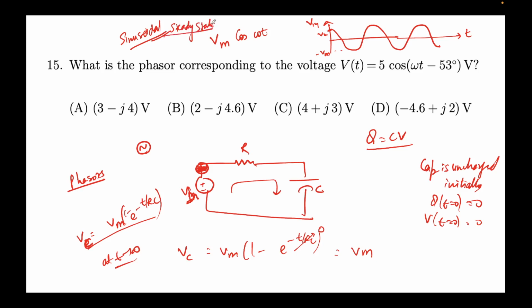This means that it's oscillating nicely over some reference like this. The output would, just like the input voltage, be sinusoidal, yes. It's not constant. It's varying with respect to time, sinusoidally, but it has achieved a steady state. This means its average value remains constant. So, for instance, this V in signal has an average value of 0 volts, right? So this output voltage will also achieve that steady state.